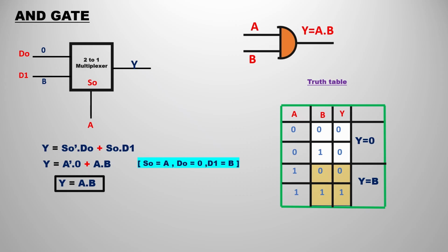If you observe the first 4 boxes, in the B and Y comparison, Y is just 0, 0. So our output would be just Y is 0, because we do not have any relation between Y and B. Y is just changing from 0 to 0. That is the reason we have the output expression Y equals 0. If you have any relation with B, then take that relation. That's the second case, which we will see, but Y equals 0 for the first one. So D0 would be 0. I have represented that in the 2x1 multiplexer also, you can observe there.